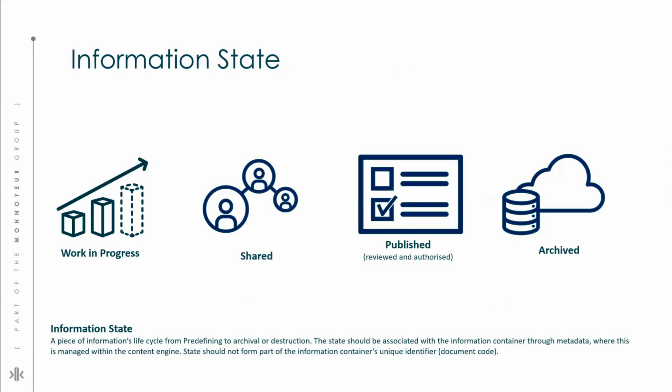So what is the ideal configuration for a project? It will be the ISO 19650 standard, which divides the project into work in progress, WIP, shared data, published data, and archive data. So what happens here is the process dictates the configuration of the project, not the type of content. We don't divide content based on what is inside each folder. We don't say this folder is for oranges, this folder is for apples. No, we say this folder is according to a process.